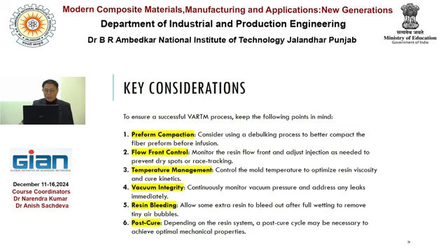And the resin bleeding. Resin bleeding means some extra resin should leak out, bleed out. Otherwise, it will make epoxy-rich zones inside, which will give a very weak structural zone. Yes, so we must be careful.